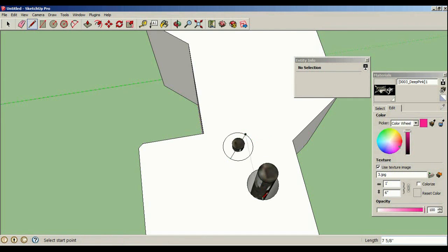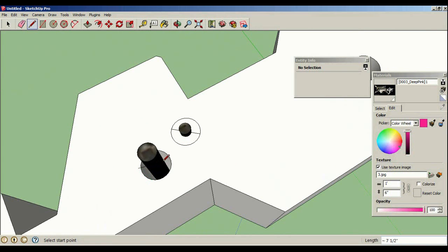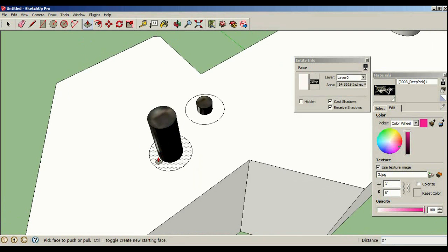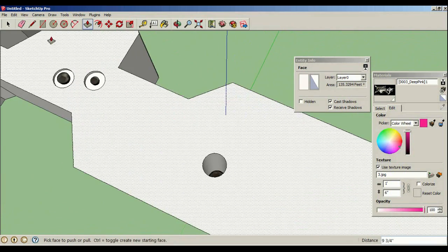So we're just closing these holes so that we still have the detail. I can close it. There we go. And delete these lines once we made them, because it will still manage to keep the face of the plane there, and then just shrink down these things, and we have our screws, buttons, whatever they are.